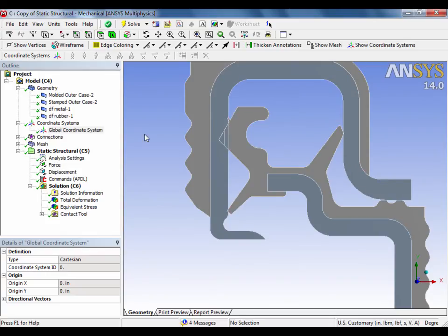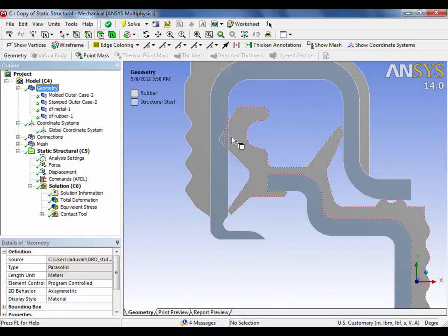Here you can see the light gray parts are both rubber, and you have quite a bit of interference between this rubber part and this metal. And the physics of the problem is we want to put a kind of an annular spring in this slot right here, such that we have a force in the negative x direction that's going to tend to push this rubber part into the metal part, because we want a fluid seal. We want to make sure that particles in fluid don't get from one side, this area here, to the other side.